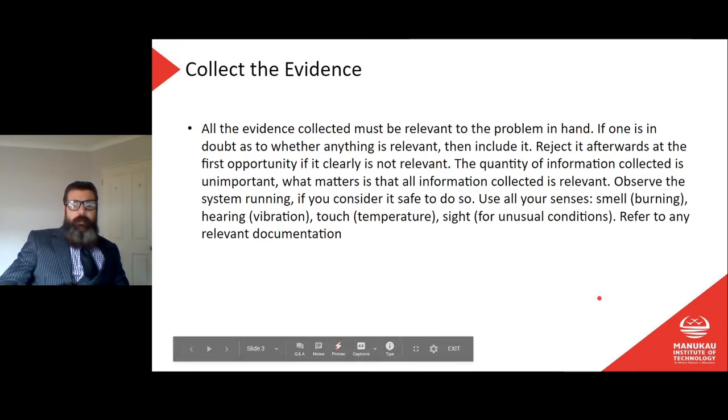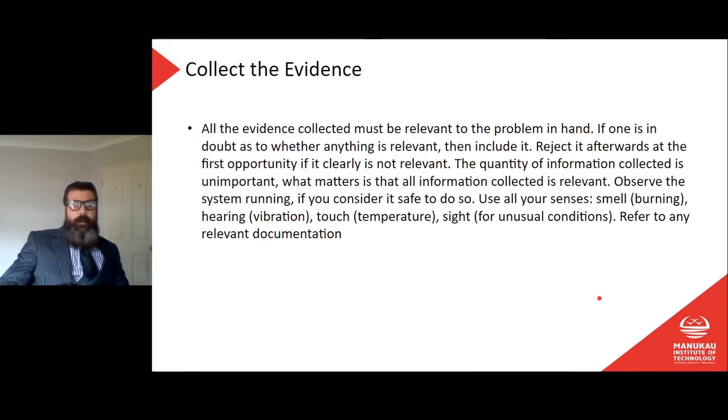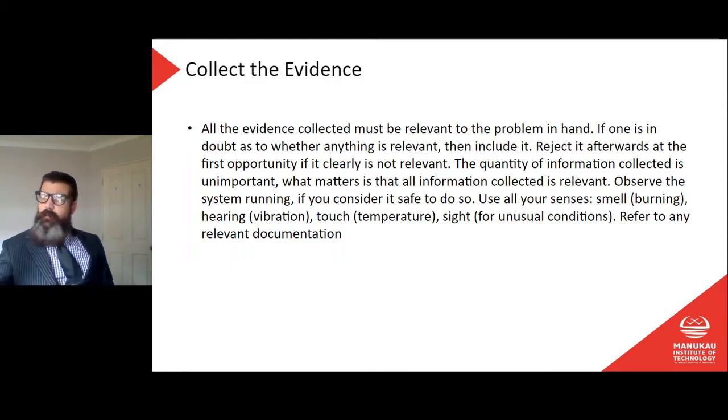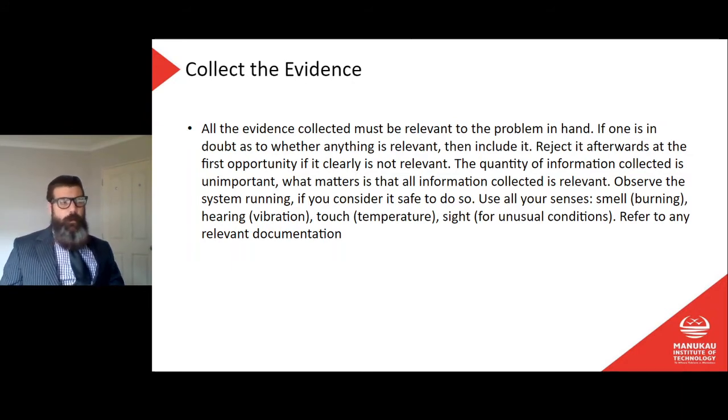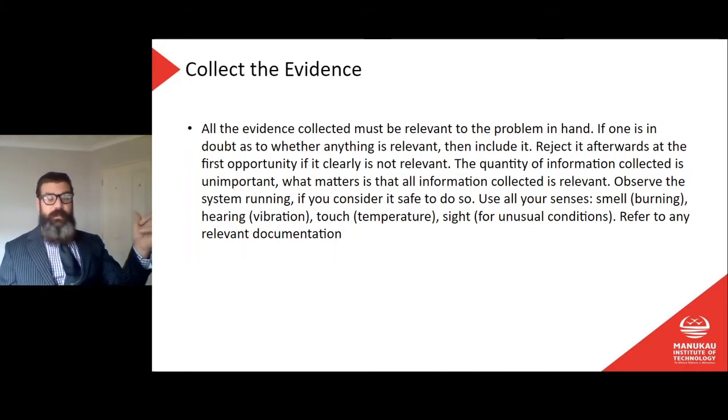So collecting the evidence. This is part of our gathering information. All of the evidence collected must be relevant to the problem at hand. If one is in doubt as to whether anything is relevant, then include it. So if you don't know, you go, there's a scorch mark on the inside of the switchboard. I'm not sure if that is relevant or not because I don't know how long that's been there. You'll open lots of switchboards and find burn marks in there, but that could have been the last time there was a fault or 10 years ago. So I don't know. Well, if you don't know, then include it.